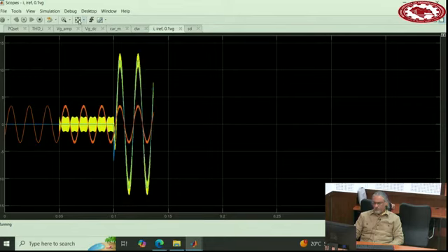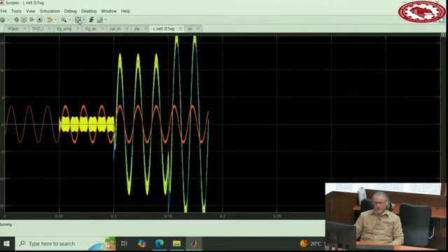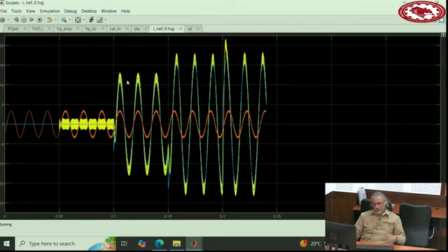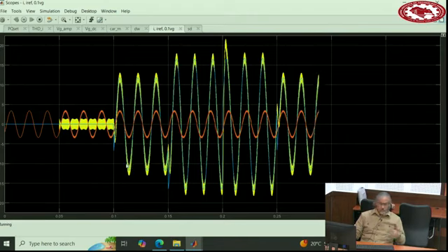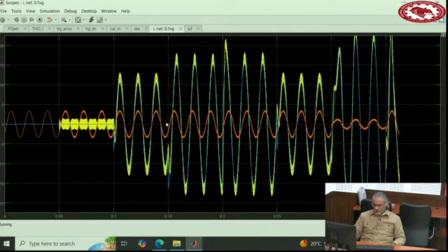It's basically the grid voltage, the converter current, and the reference current that is generated. The yellow one, which has switching noise, is the actual current of the converter, and the blue one, which doesn't have noise, is the reference for the current. I show a factored version of the grid voltage as this brown figure here.